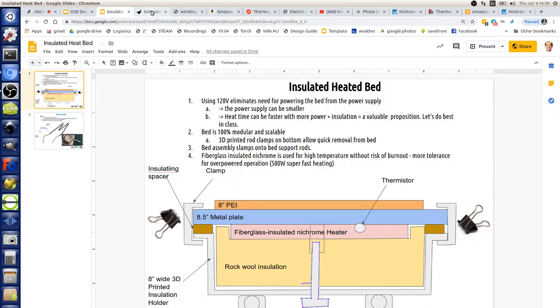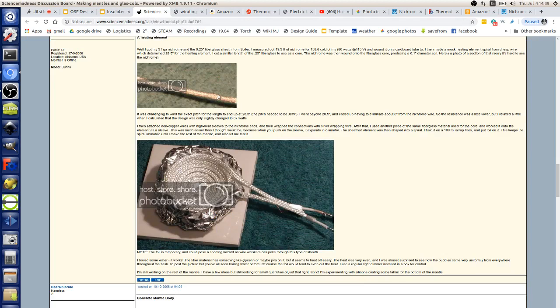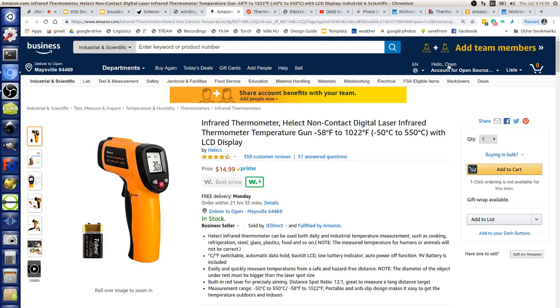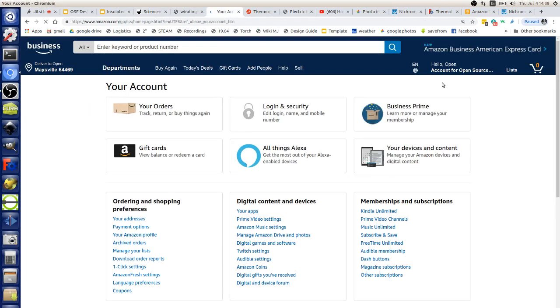Last thing, so let's talk about the filament maker. We talked about filament extruders this morning. But for the filament maker, it is very convenient to make a nichrome heater like this, where you have a nichrome heater that's whatever power you want. And that does turn out to be lower cost, because nichrome wire, I mean, how much is it? You Google on Amazon. It's always talking about the cost engineering here. What's your cost for these heater elements? We said it was 30 cents a foot for the sleeving.